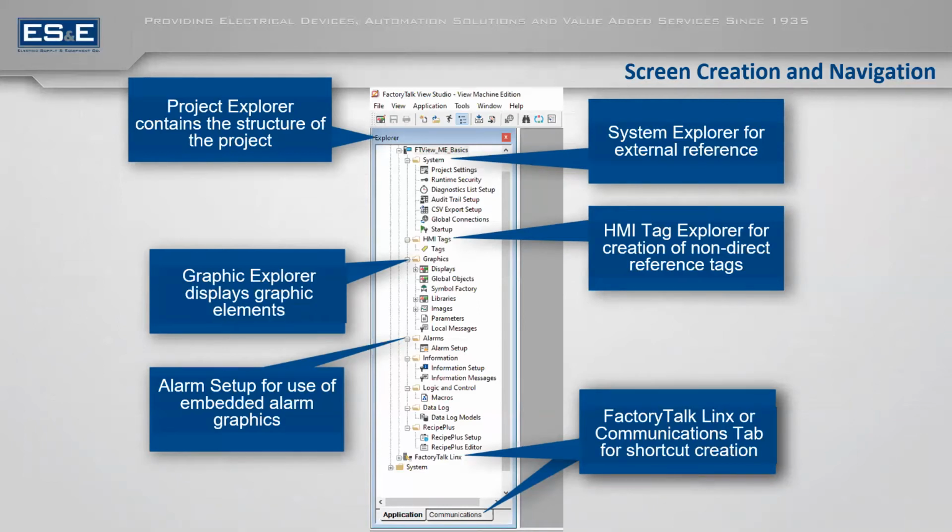And on the display, you can tie those directly to an object or a tag name straight in the PLC. Now the syntax gets a little weird because you have to have brackets around your topic or your communication path. So some people don't like to see that on the display. They would prefer to see just a normal tag name, and then therefore you need an HMI tag separately. That's really a preference thing depending on who you're talking to.